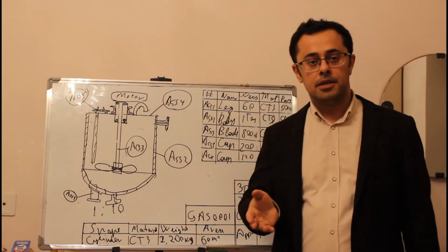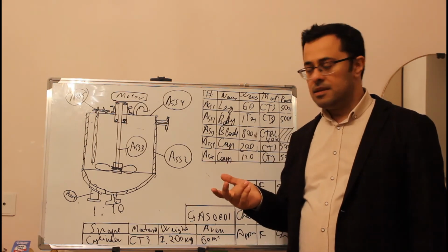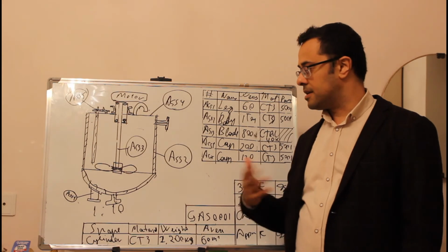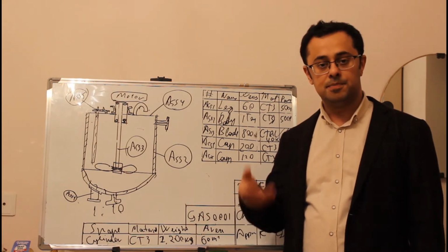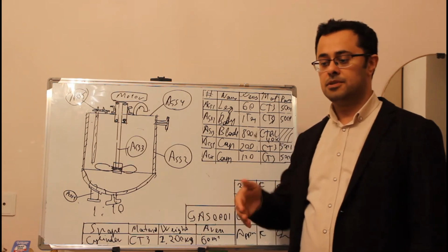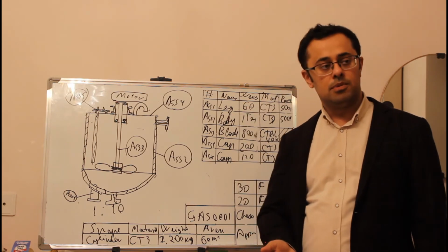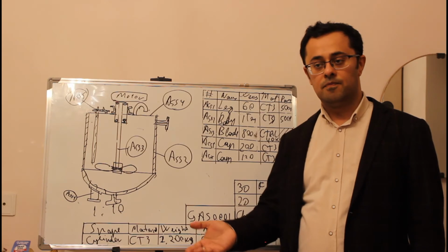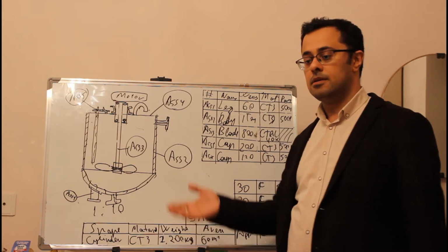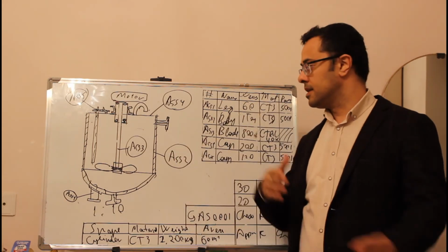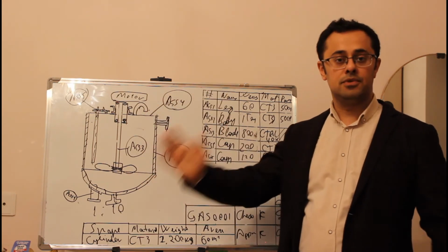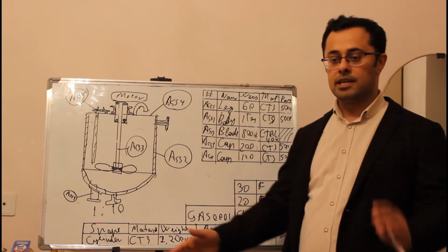So the blade. For the blade they need something extra, like plasma cutting CNC machines. So they put it on the plasma cutting CNC machine, then machining, then welding. They also use a turning machine for the shaft, so turning, then assembling.